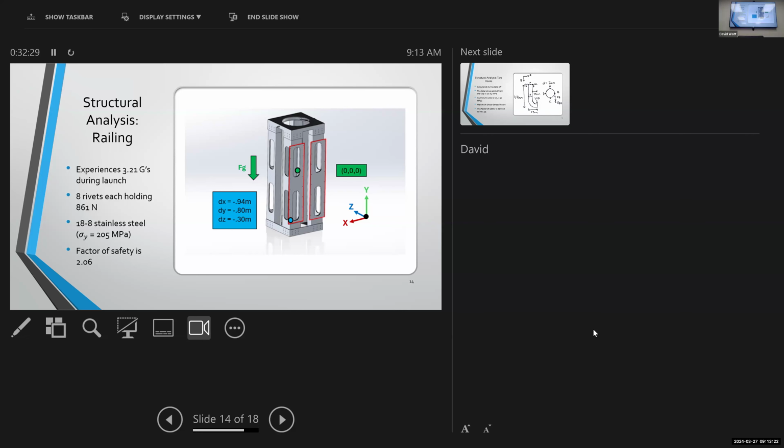Your factor of safety here is 2.06. What's your requirement? For us, we had an initial requirement, I believe, 1.5. 1.5 on what? Just that was our general factor. Fair point. We chose 1.5 as the general factor of safety for all designs statically, so in terms of structural. So for that, if we were around that ballpark, then we were happy with it. We kept it at 2.06 just because we wanted the number of fasteners to be not like 4.